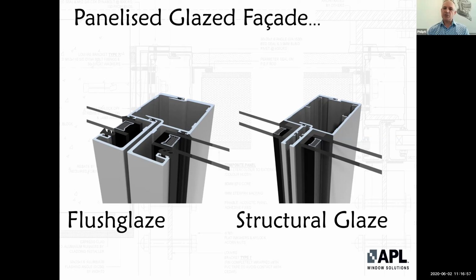Now, there are some benefits to using a structurally glazed system, and that is simply that when it's fitted into place on the side of the building, it makes the space behind it directly available for other subtrades to use. So it has a positive net effect on the building project. It comes a little bit more expensive, so it's a bit of a premium, but I think it's offset by the potential gains you may have in the lead times.